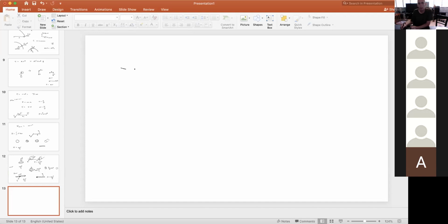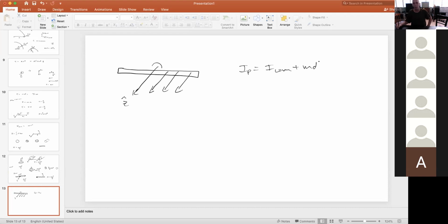Now, for the rod, if I go through the center and this thing rotates around, I could choose another parallel axis at any point, and I can figure out the moment of inertia around any other parallel axis, in the same direction as z but located somewhere else on the rod, using something called the parallel axis theorem. And that's ICOM plus md squared. For the rod going through the center, ICOM is ml squared over 12, plus m times d squared.